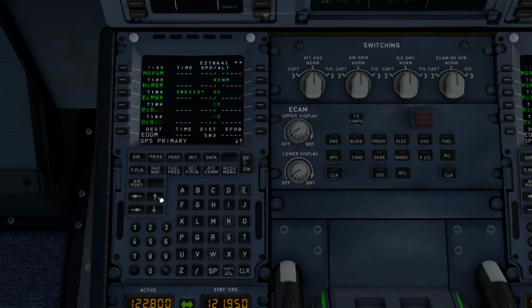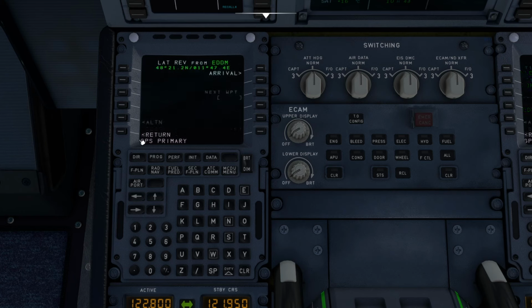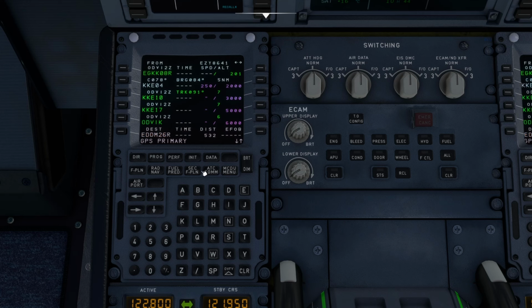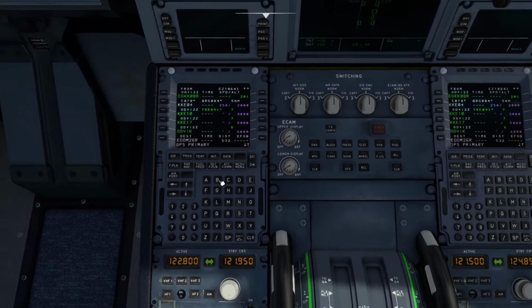And then we have a whole flight plan all the way down to Rockhill, and then a discontinuity to Echo Delta Delta Mike, and that's where we can stick in our arrival. So let's choose our arrival again. We're going to go runway 26 right. We're going to use the Rockhill 1 Bravo departure via Mike. Insert that.